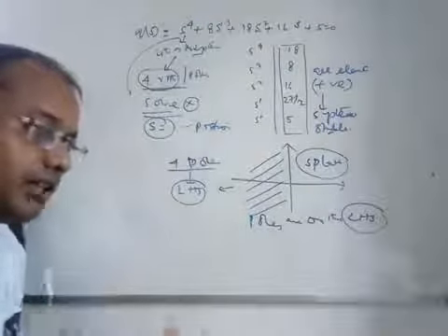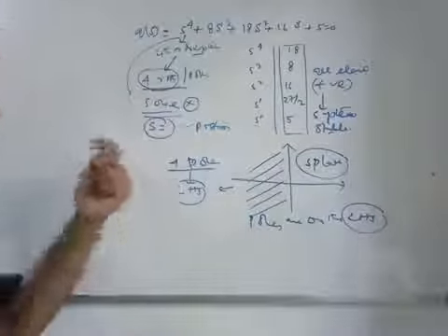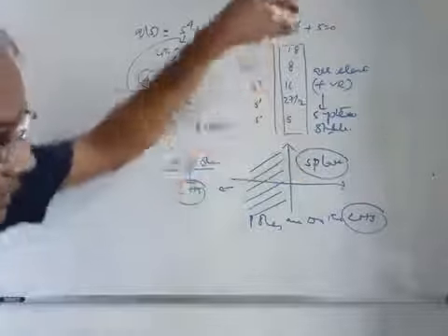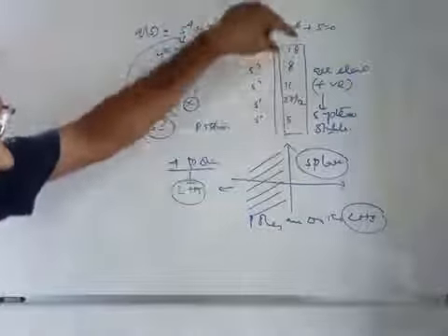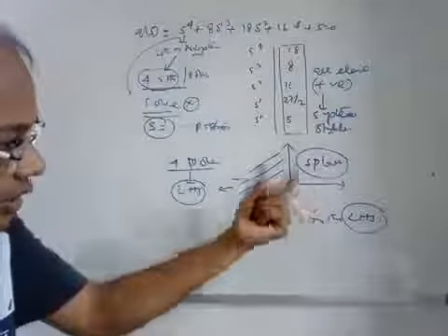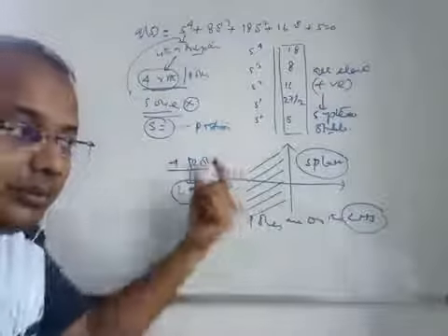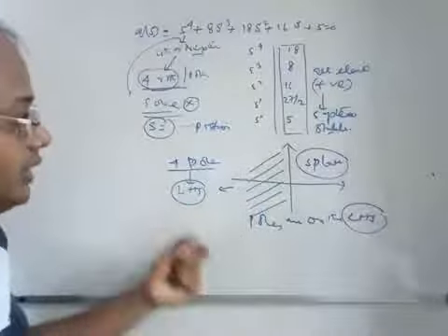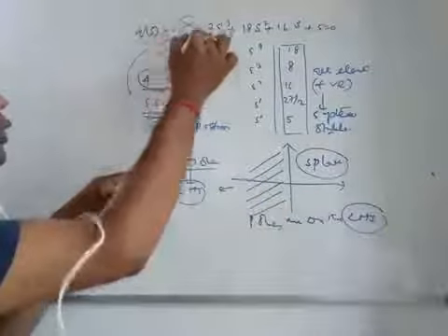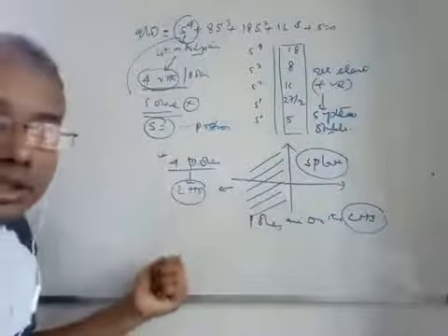If you are asked to comment on the system stability, what does it mean? It means that if all the elements you found from the Routh array, the first column elements, are positive, then the system is absolutely stable. That means all the poles are lying, in other words, on the left hand side of this plane. If the poles are lying on the left hand side of this plane, the system is stable. That means there are 4 poles, as this is a 4th order system. So 4 poles or roots are lying on the left hand side of this plane.